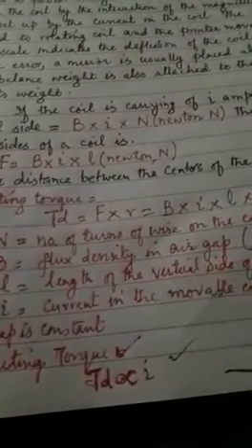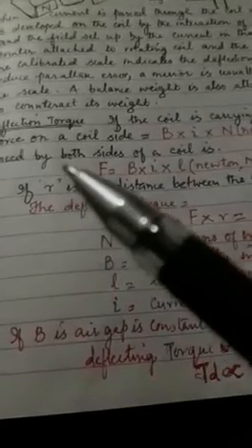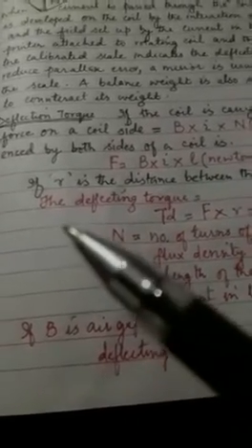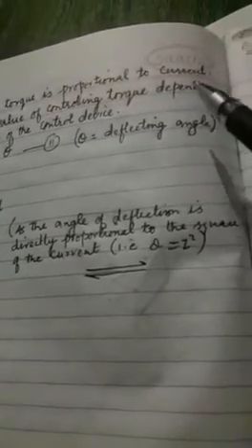You see what I am writing here, so you can get this note clearly written and then remember it. Equation first: deflecting torque. Controlling torque is proportional to theta, equation number second. Then, in equilibrium, comparing these two, theta is proportional to I square.